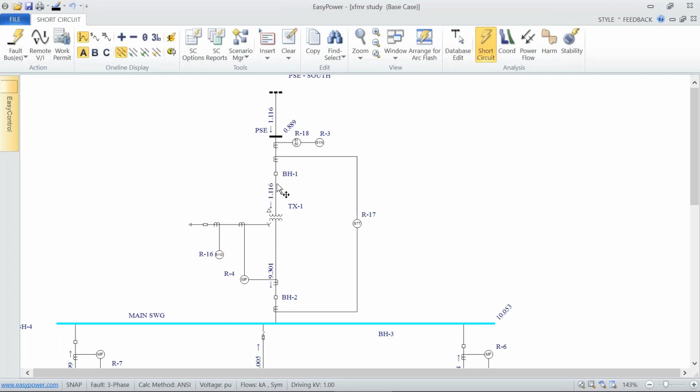So we just bump this up by 10%. So we can set an instantaneous value then for this relay at 1200 amps, because we know anything greater than that, there's a fault on the primary side, and it has nothing to do with the secondary side. So that's where we'll set our instantaneous rating.